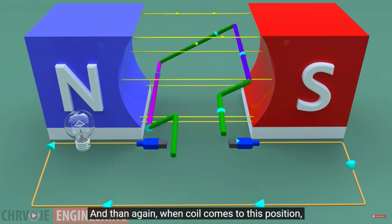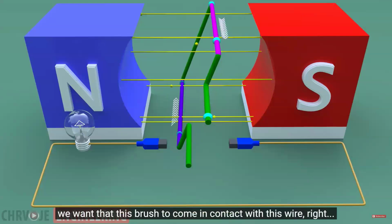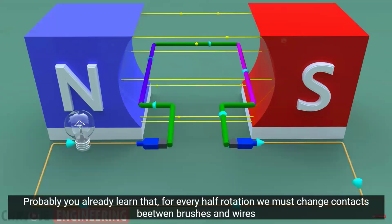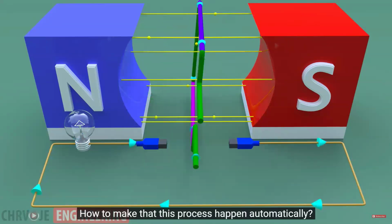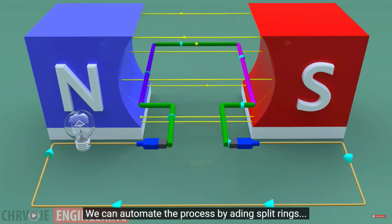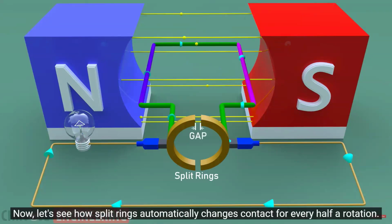And then again, when the coil comes to this position, again the direction of the current changes, and again we want this brush to come in contact with this wire. Probably we already learned that. For every half rotation we must change contacts between brushes and wires. But how do we make this process happen automatically? We can automate this process by adding split rings. Split rings, as the name suggests, is a ring that is split in between, giving two half rings with the same gap in between. Now let's see how the split rings automatically change contact for every half a rotation.